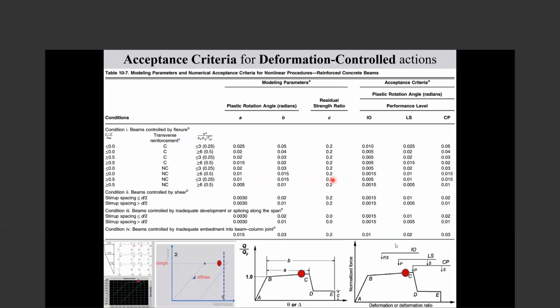But there is a chapter completely on modeling the soil with springs, which is very, very nice. And many times if you use those modeling, the same that you mentioned, beam column, or soil, the performance of the building improves. Because when the connection to soil is very rigid, usually damage concentrates.